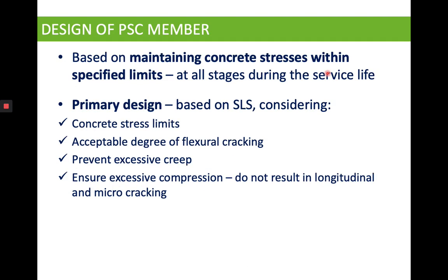We will begin with the introduction to the design of a pre-stressed concrete member. It will be designed based on maintaining concrete stresses within the specified limits at all stages during the service life. We know that for a pre-stressed concrete member, we are going to consider two types of conditions: one during transfer, as well as during service. We have to bear this in mind, whereby we maintain the concrete stresses within the limits. We are going to discuss the limits later.